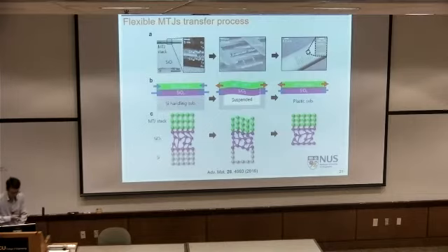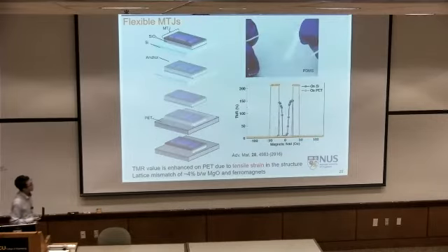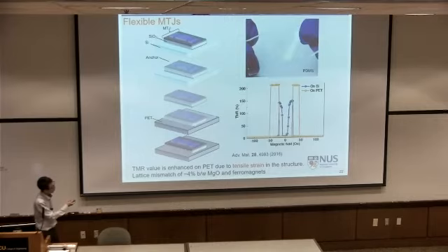Once we have a tensile stress, we expect enhancement of TMR. So in fact, this was observed. If you look at the MTJ on top of silicon, we have a black curve as a function of TMR and magnetic field. But as soon as we move this onto a plastic substrate, you can see the TMR improved immediately. And then also the loop response became much more square.